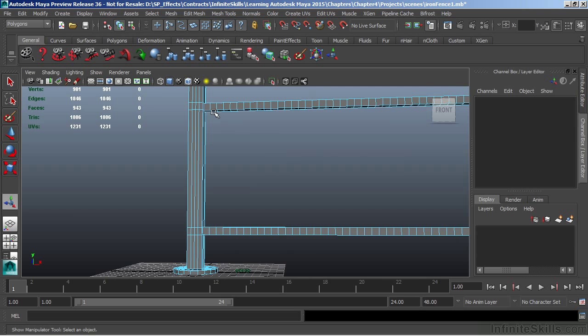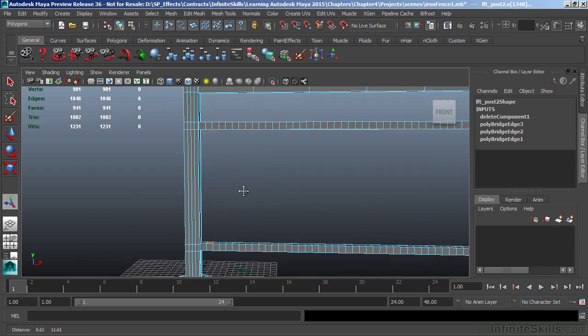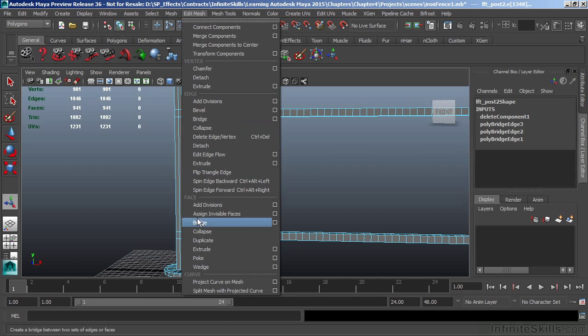We're just going to keep that as the default. And I'm going to select one face there and its opposite face on the other side. And I'll choose Delete to delete those faces. And let's go to Edge, double click, and double click to select those two borders.